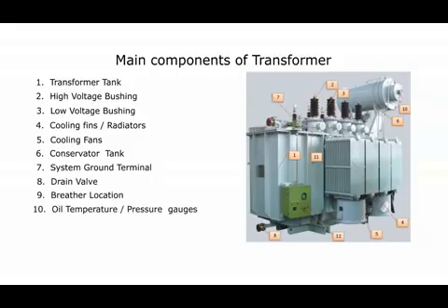Oil temperature and pressure gauges are used for monitoring the internal characteristics of the transformer, especially its windings. These gauges help the operator in knowing the level of temperature and pressure inside the transformer, oil and winding. This will also serve as an alarm whenever a certain level is reached that could be harmful to the transformer windings. Bushing current transformers. Modern transformer construction today now includes current transformers.